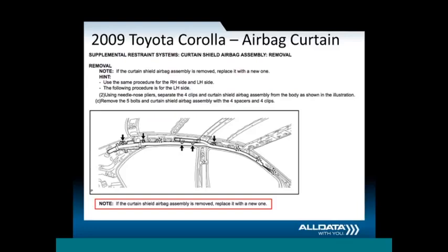Well, when our technicians go to weld and hook up the ground for their welders, that welder is obviously putting out much more than 12 to 14 volts. So it's putting out more of a charge or surge than the system is designed to handle. Therefore, if we have any electrical components within 12 to 18 inches of the area where we're welding, we could be sending more of a power surge through the system than it's designed to handle, and thus it could damage some of the electrical components.